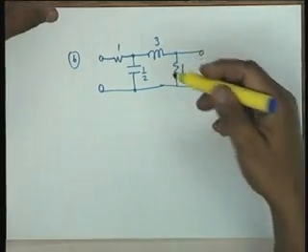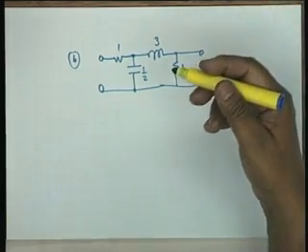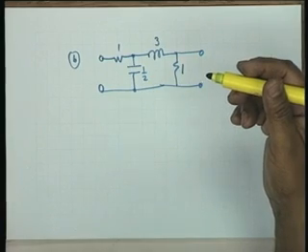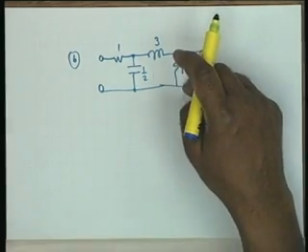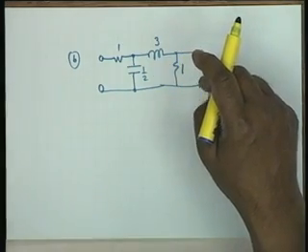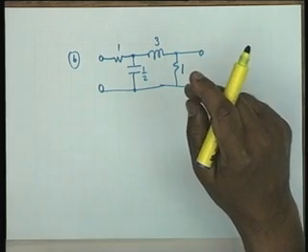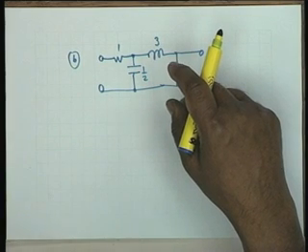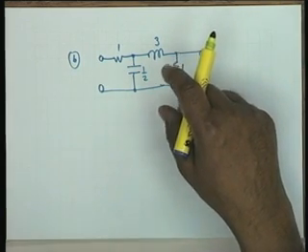This is not an RC, RL or LC network. This is an RLC, and it says that the residue conditions are valid. You have to show them. So, previous one was RLC. Yes, that is correct. Previous one was also RLC, but fortunately the poles were only on the j omega axis, s equal to infinity and s equal to 0. So also the RLC circuit may satisfy residue. May satisfy, may not also satisfy.